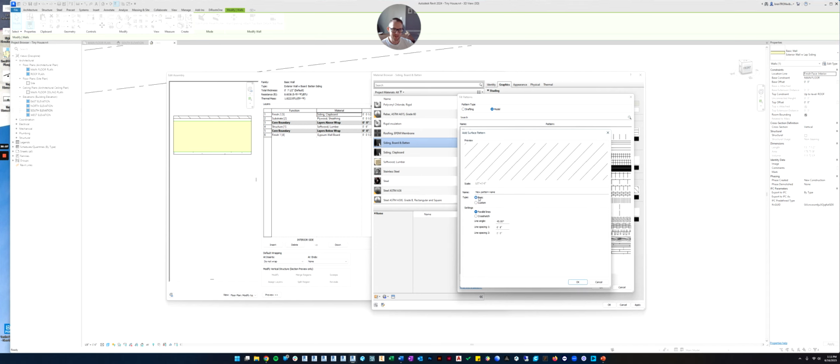So you'll click it back to basic, and we'll name it 6-inch vertical lines. Okay. And now down here, you have the basic settings. We do want parallel lines, or you can do a crosshatch and it adds perpendicular lines, but we want parallel lines. And then we don't want it to be angled, I don't think. Oh no, we do. So 0 degrees puts it horizontal. That means we want it 90 degrees, so we want it running up and down. And then you can pick how far apart the lines are. We said they were going to be 6 inches, so we'll type in 6 inches. Now it'll draw the lines 6 inches apart. Now we're going to click OK.